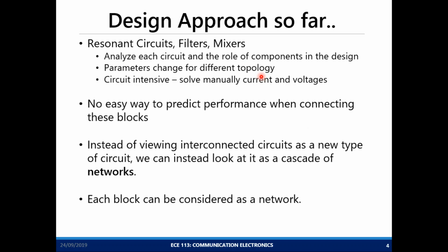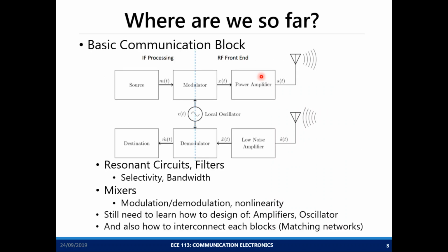The problem with that is in system level view, there is a loading effect between different blocks in your circuit. The output impedance here could be affecting the input impedance here. And the performance between your blocks could be suboptimal.